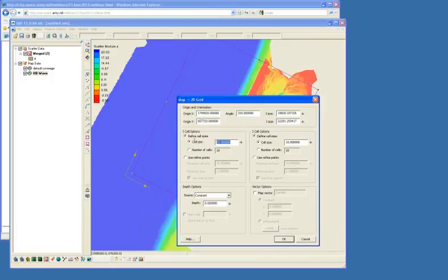We want to have a maximum cell size, and yesterday we were using 180 meters, and we can use the same thing today if you want. We could go up from that. We will be using refine points, so let's make sure that that's selected. I'll enter these values again. And I'm just going to leave the bias alone, turning off these checkboxes for the inner growth. As I specified the other day, that inner growth means that between where I have the refine points, the spacing will be kept constant as much as possible. They will not grow larger than a certain size.